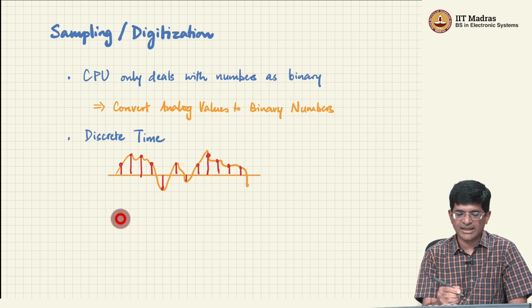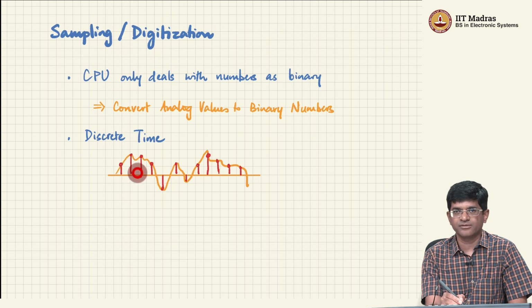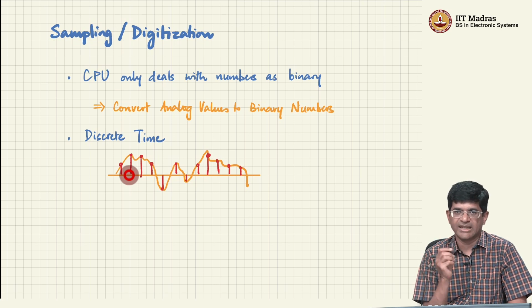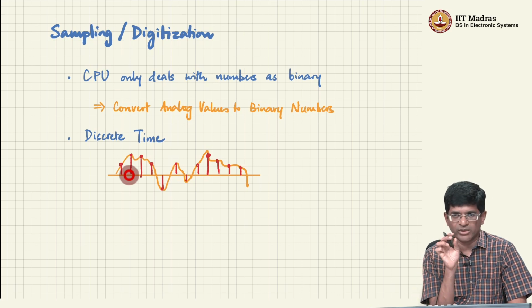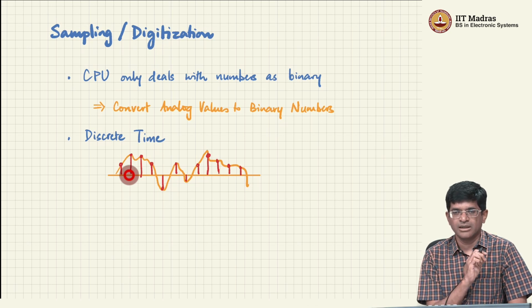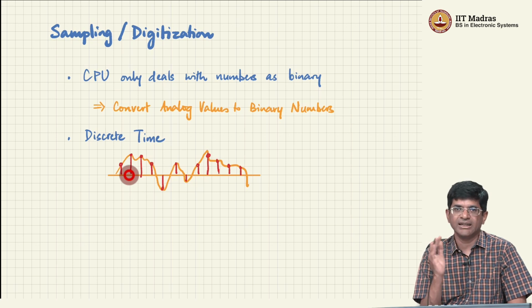I'm making the assumption that if I have sampled often enough, I will be able to answer the question. If you ask me what was the value at the instant 1.267395 seconds after the system started, I don't know, but I do know what it was at 1.23 and 1.24 seconds, and from there I can make an interpolation and say, hey, it was probably close to this. So I don't really know the value at each and every instant of time, but I know it at sufficiently many instants that anything else I can interpolate and tell you what the value was.